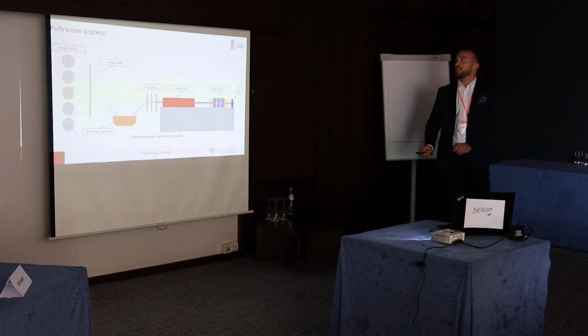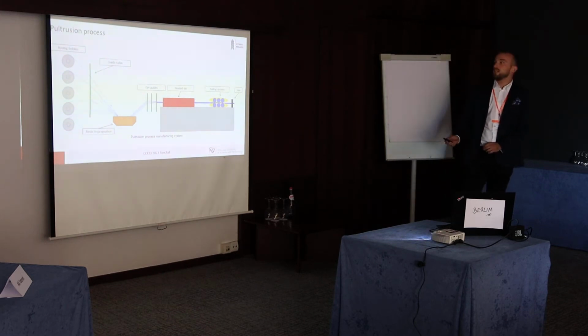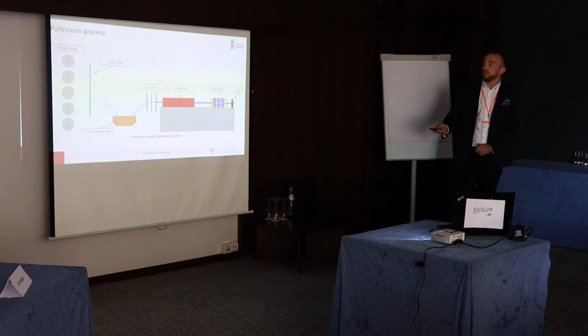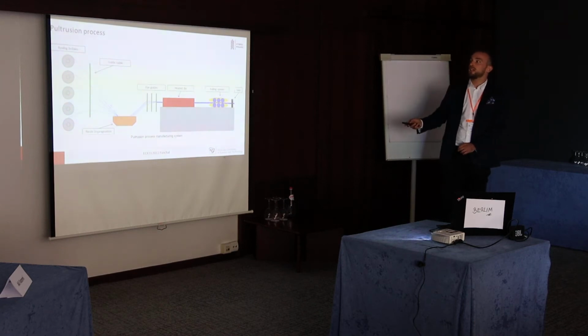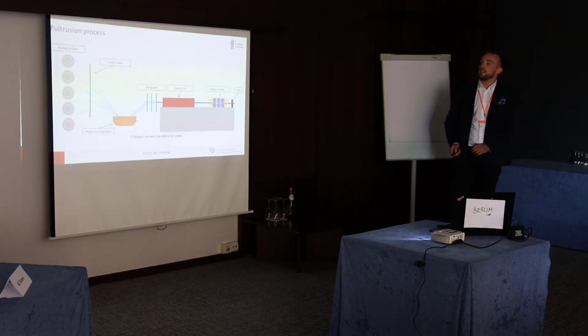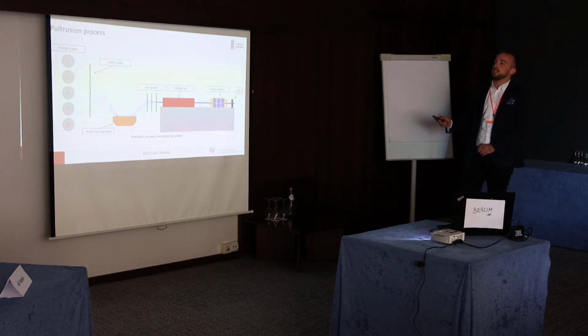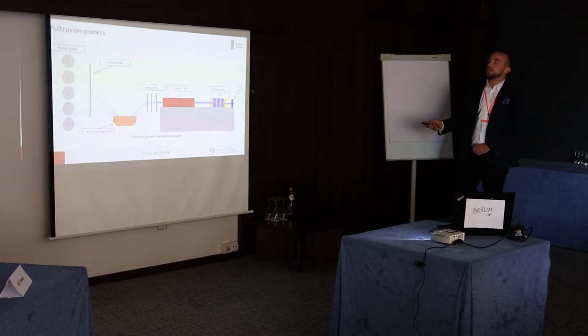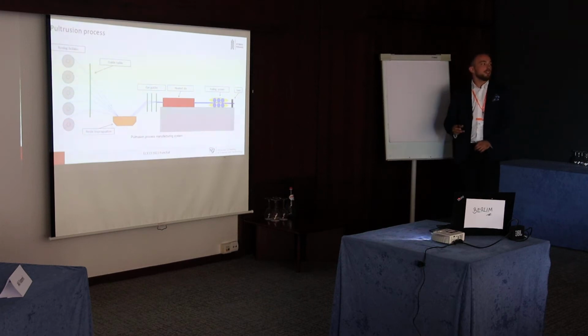Okay, so the pultrusion process is a continuous manufacturing process of composite profiles. In the beginning, we have the fibers in the shape of bobbins. The fibers go through the guide table to the resin bath, which could be warmed, and in this resin bath the fiber is impregnated. The wet fiber goes through a guide and is pre-shaped to the cross section of the profile.